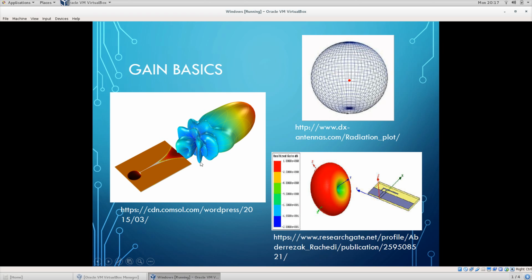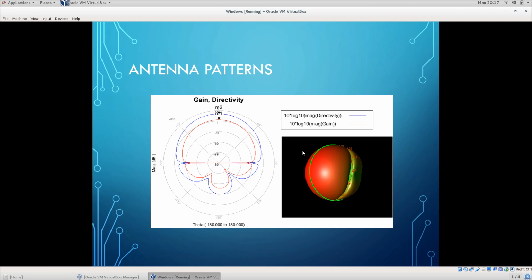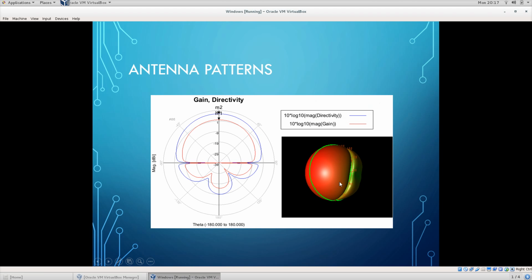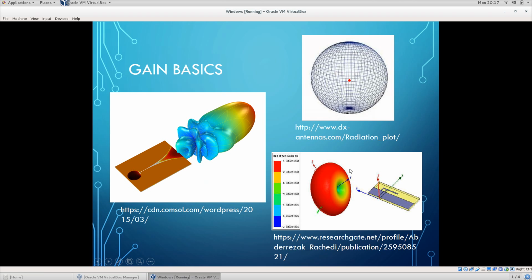It's hard to say for sure because I don't know what the characteristics are. This antenna here is an omnidirectional antenna. Right? Now, the reason I'm saying it's omnidirectional is because in some particular plane, if you remember going back up to this one, I cut it this direction. If I were to make the same cut that you see here on this antenna, then what you'd see is effectively a circle. Right? That's actually pretty good for an omnidirectional antenna, assuming that you're in one plane.